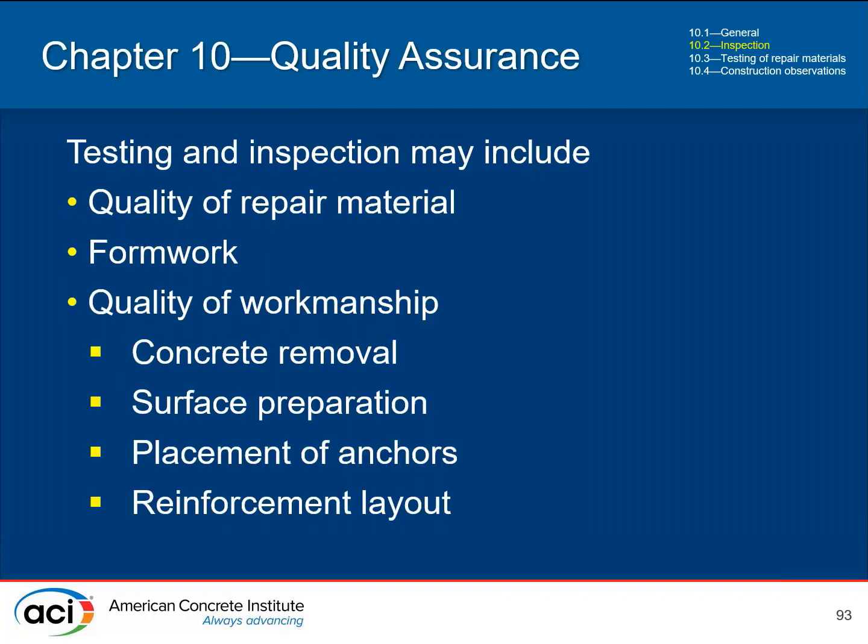Just some of the ideas that testing and inspection may include, nothing earth-shattering here. You're looking for the quality and that it meets the design intent. So, quality of the repair material, the right formwork, whether the concrete removal is done correctly, whether you end up with the surface prep that you need, and whether your formwork and your anchors and your reinforcement are in the right place. Normal things that come as part of an inspection program.